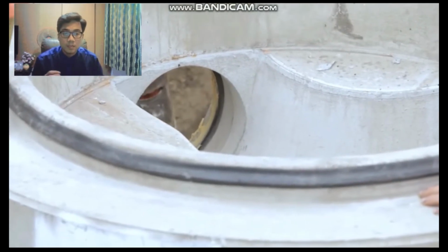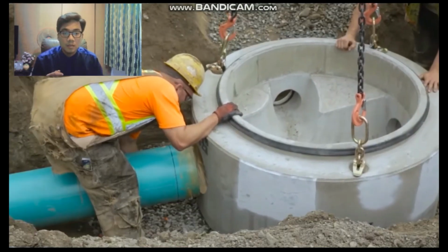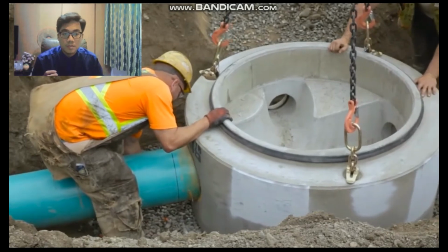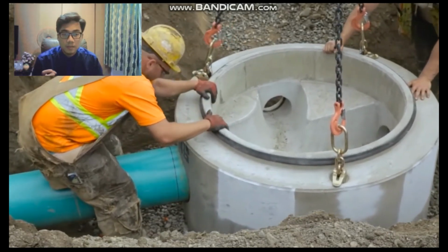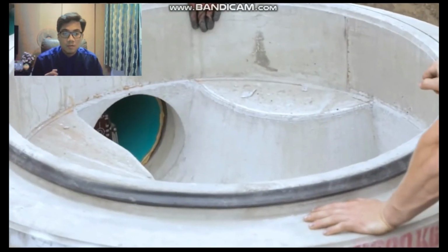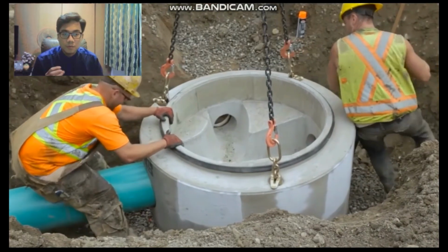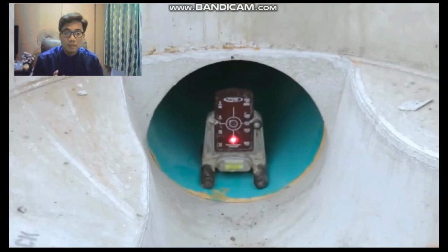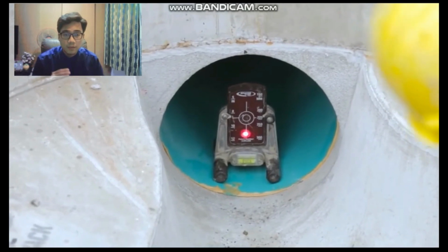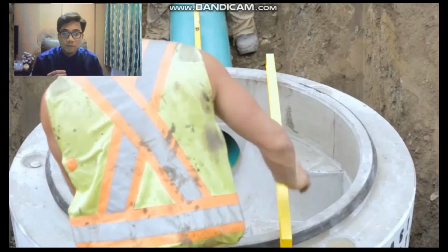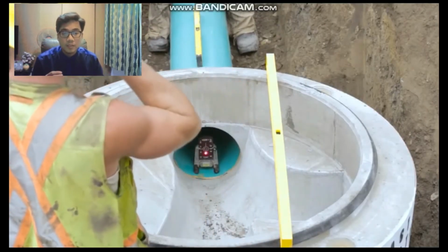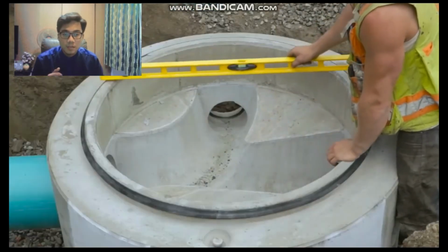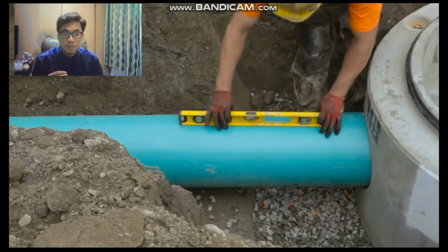Align the base outlet with the pipe and push the hanging manhole base so that the pipe enters the outlet. Once the alignment is confirmed, push the manhole base home until the pipe butts firmly up against the rear of the third step of the outlet. Often a pry bar is used to aid in this step. Once placed, ensure that the manhole base and downstream pipe are level.